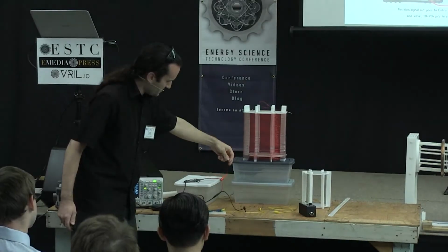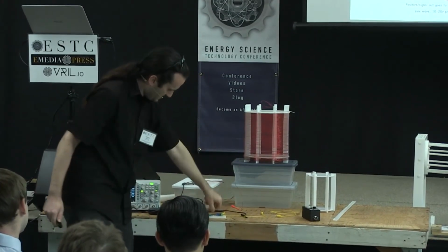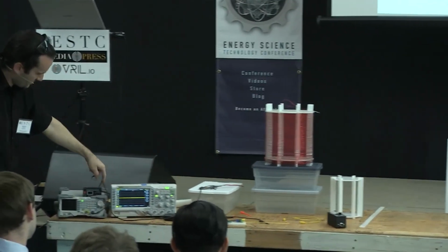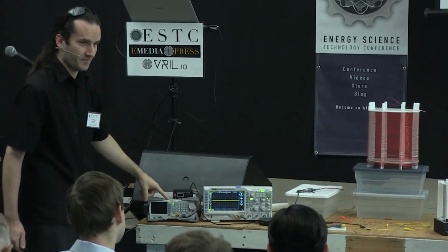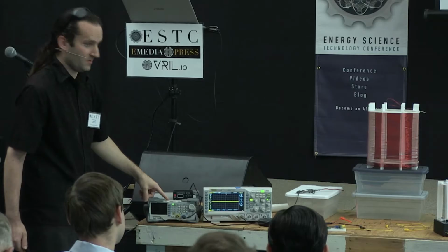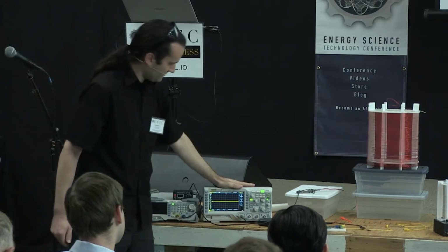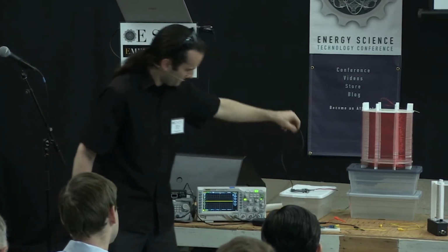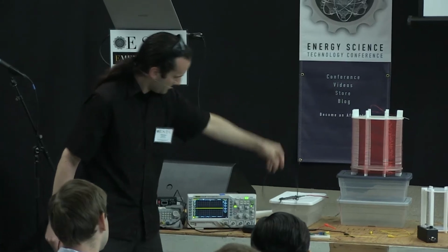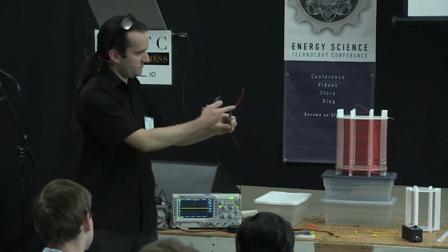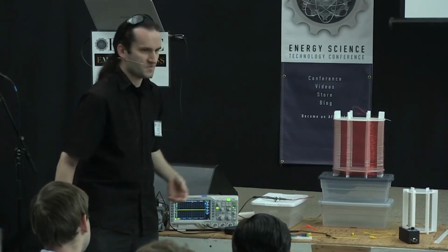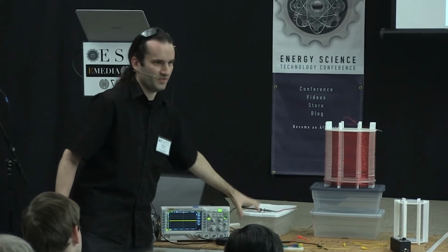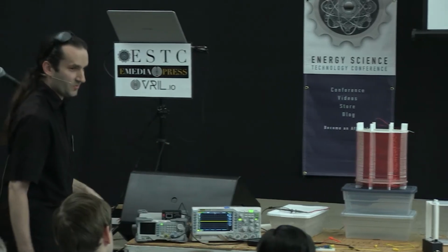The wire leads to the positive lead, which if we trace it down, goes to this little power meter, which goes straight into this function generator here. Function generator is very low power. And then to pick up the signal and help tune it, we have an oscilloscope and a probe, a little short piece of wire. None of this matters. I'm just going to let it sit somewhere near the coil, and it'll be fine, and we can actually tune the coil with this.